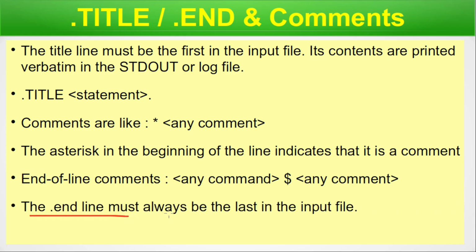The .end line must always be at the last of the input file. So this is the marker that tells the simulator now you have reached the finish line of your running. So you are running for so long and now I give you the flag to stop. So this is a finish line marker for the SPICE simulator.